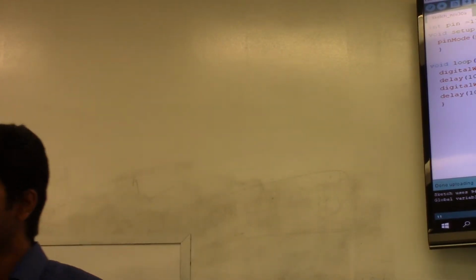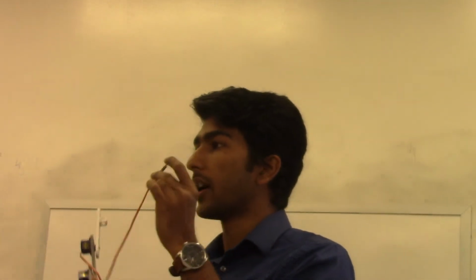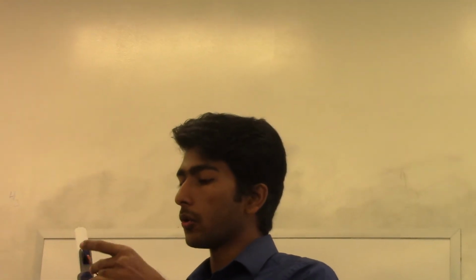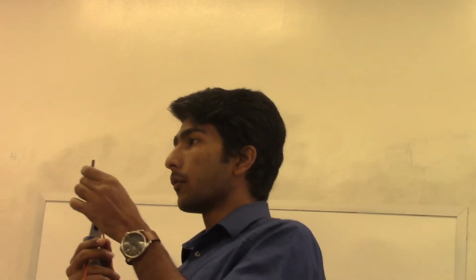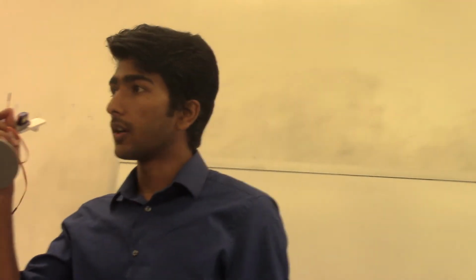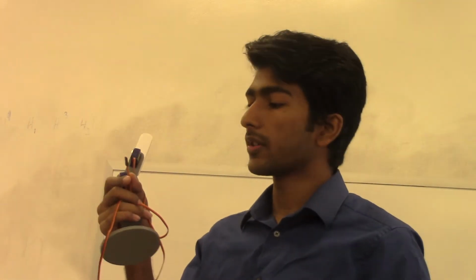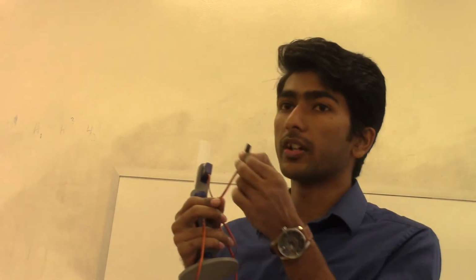So take a look at this manipulator. You will notice that there are again 3 servo motors, and each servo motor has 3 wires. So the red color wire here is the positive connection which we are going to send the 5 volts, and then the brown color wire is the ground.